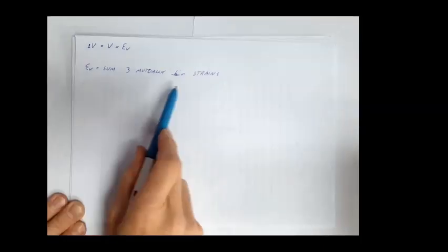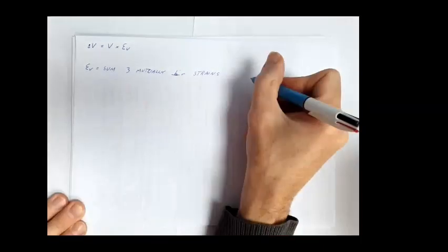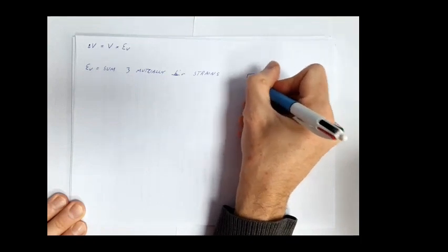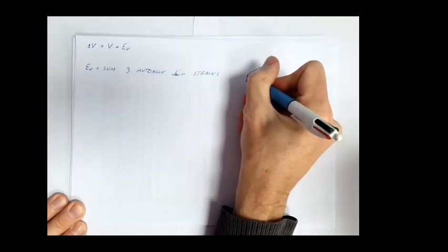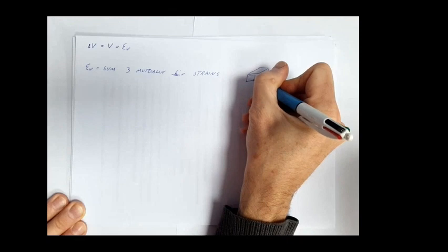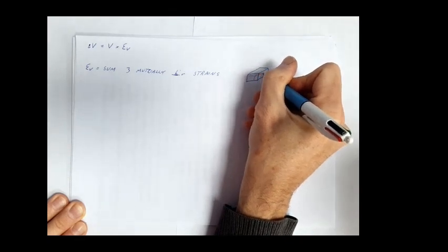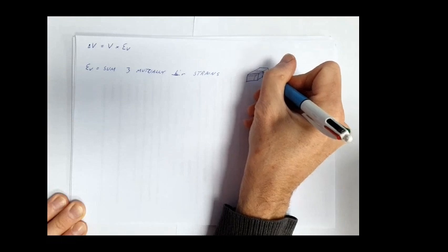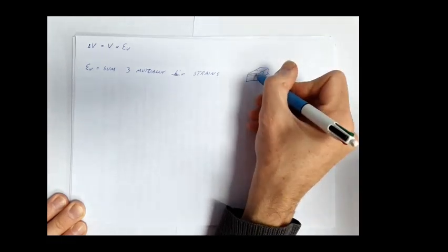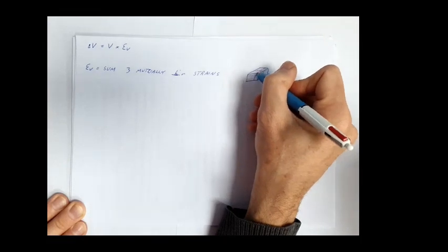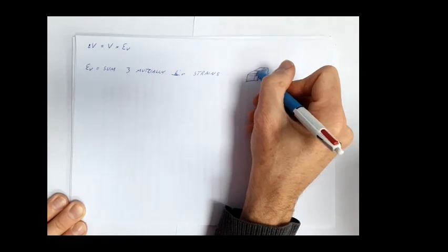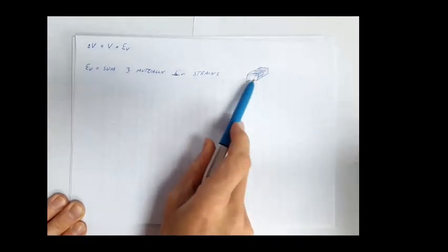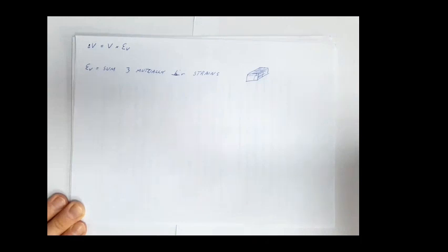Remember, we derived that last time with Cartesian coordinates, this idea of having a cube, and we then pressurized it so that it's changed shape, changed into something like this. So my strain was there, and we added those three bits together. Remember, we added the strip on the side, the strip on the top, and the strip on the back. Okay, so we showed with Cartesian coordinates how our volumetric strain was the sum of our three mutually perpendicular strains.